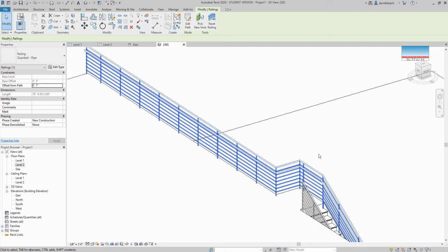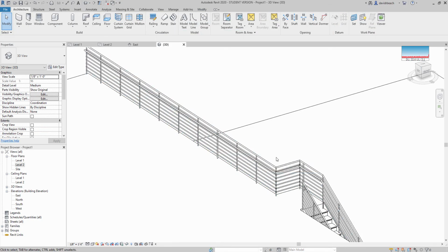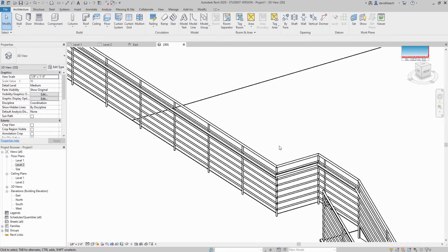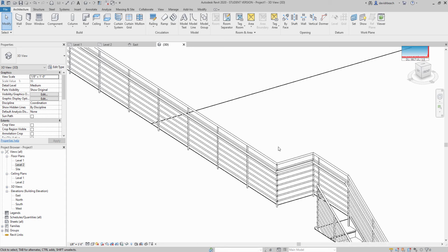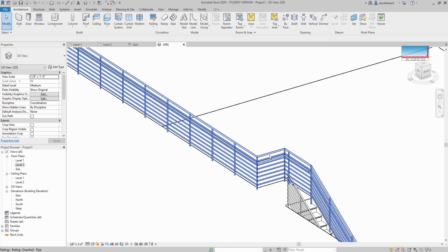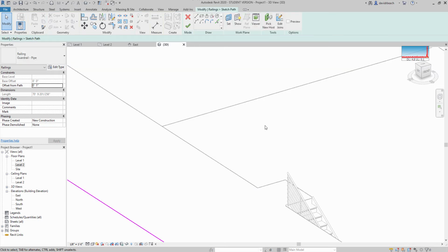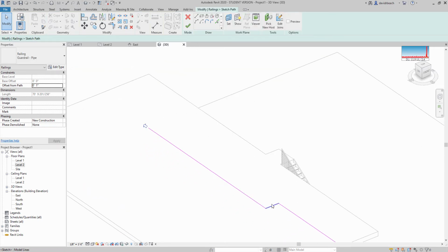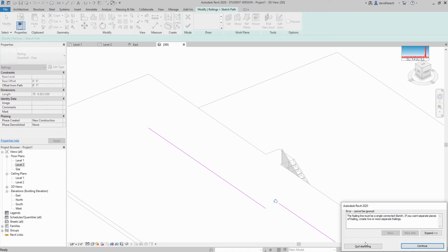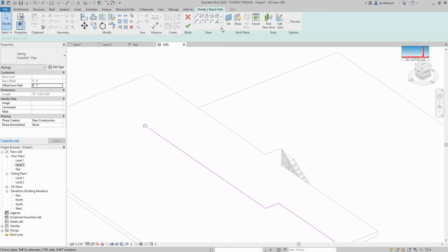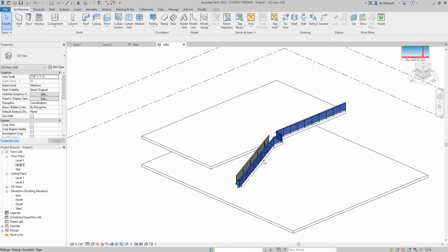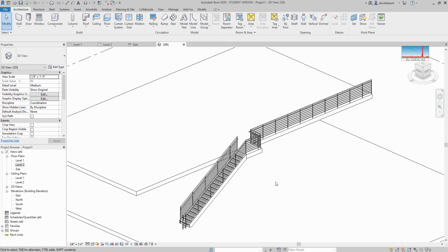Technically speaking, this doesn't necessarily need to have this handrail across, but it still needs to be at a guardrail height. Okay, so I could draw that as something separate. An important thing to note with these guardrails, they cannot have gaps in them. So anytime I have a gap like this, Revit can't resolve that in terms of building a model. So those have to be continuous lines. Let's undo, green box, check. Cool. So that's basically working with the defaults.